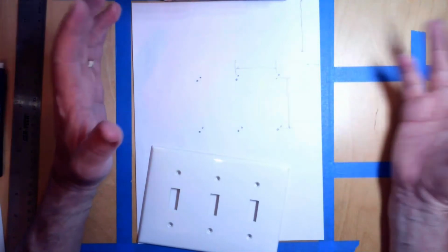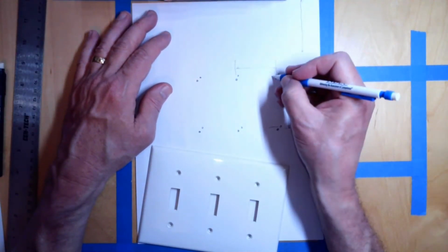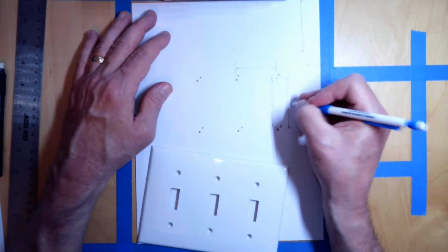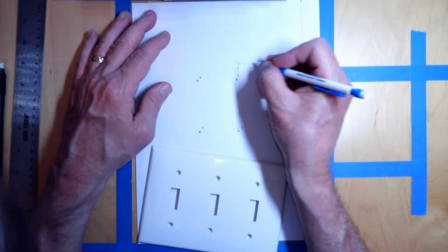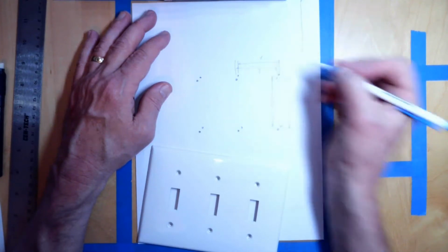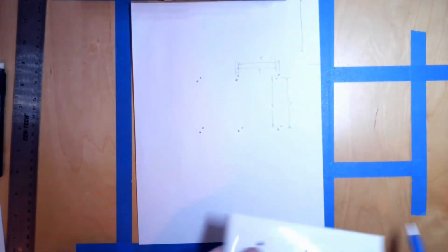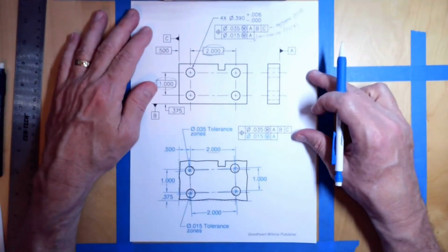We don't want to throw out our whole wall, so to speak, because we drilled the holes here, as long as this distance x is the same as this distance x, and as long as this distance y is the same as this distance y. Okay? So that's where the pattern locating tolerance zones and feature locating tolerance zones, let me bring this back in,